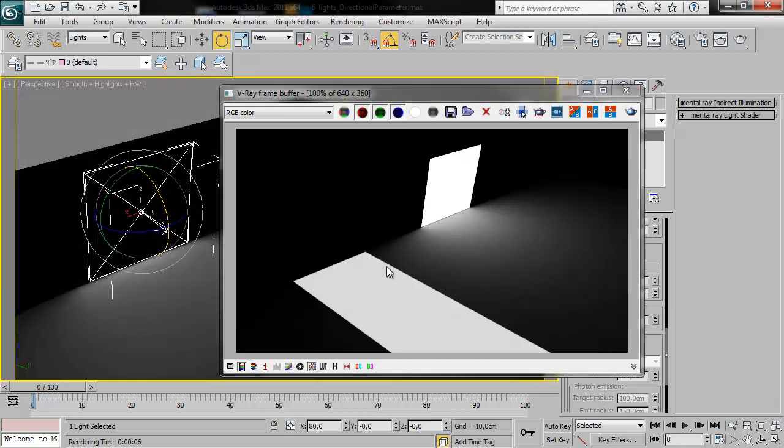So now, instead of this regular planar VRay light, you now have a spotlight. And you might notice that the light plane is now invisible, and this is actually physically correct because the camera is outside the angle where the light is visible.